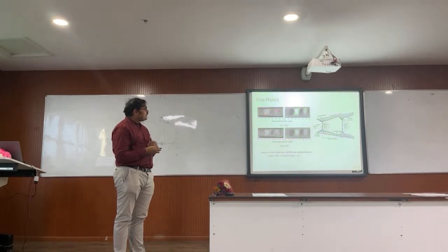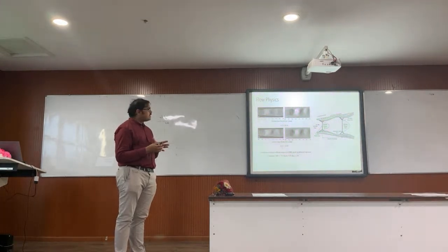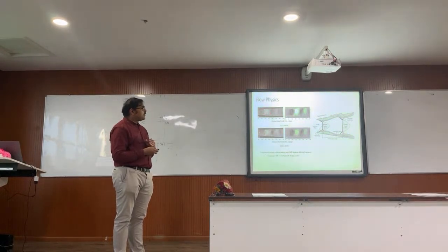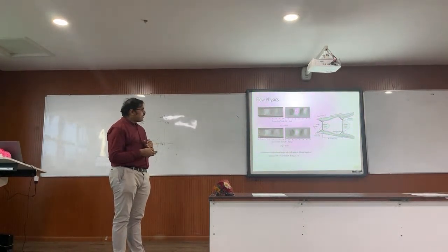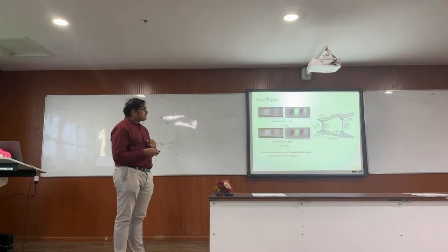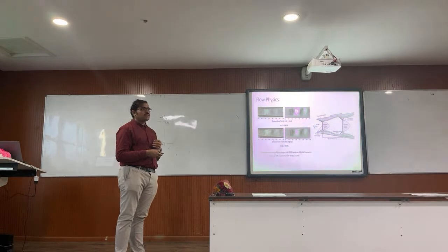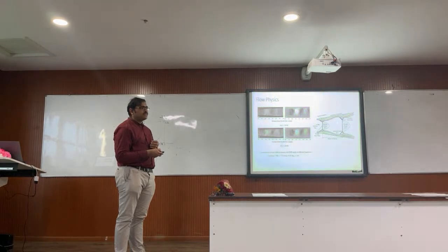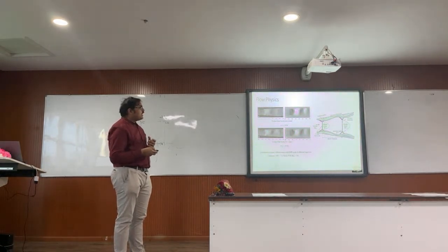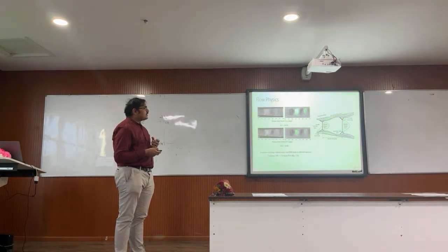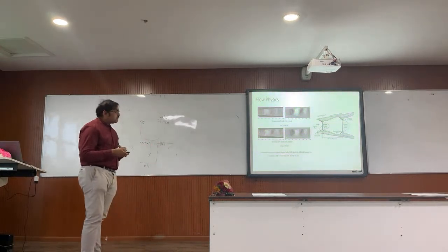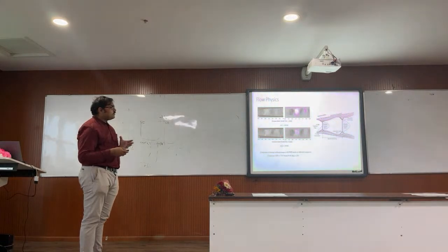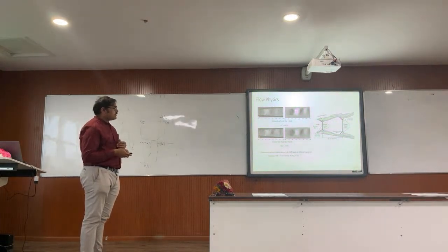Interestingly, we find that using this kind of analysis as well as EMG gives us the same shock shape. So that means there is some correlation between the shock shape and the frequency. What we found was the frequency is linked to the shock cell spacing, because there are these separated boundary layer regions, which are subsonic in nature. They can allow interaction between these two shocks, and that can set up a kind of standing mode, which basically decides this frequency.